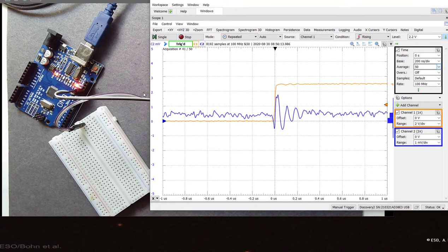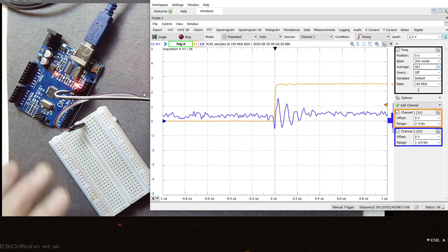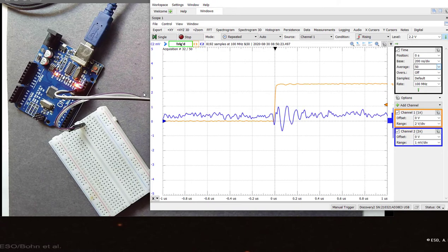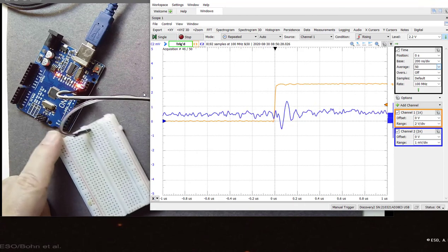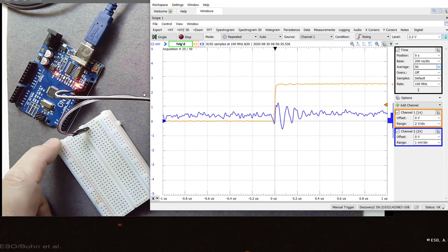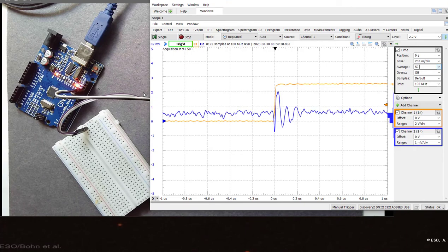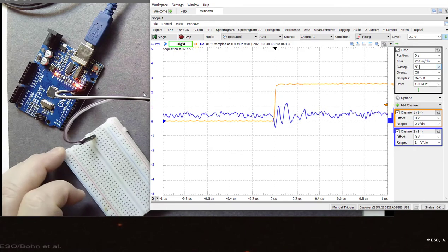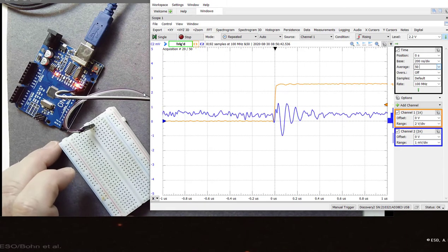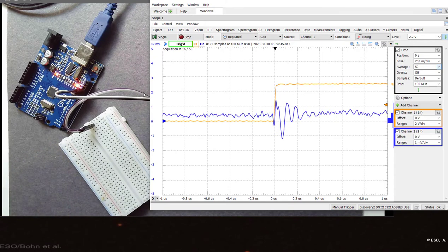And this is one of the most important reasons why, if we care about low-level noise and crosstalk, we don't want to use discrete wires between the scope and the device under test. And we also want to always be careful of minimizing the loop area of the probe between the signal and the return, and keep those two loops far away from each other so we don't have this inadvertent channel-to-channel crosstalk in the measurement system. This is an important artifact that we want to avoid.